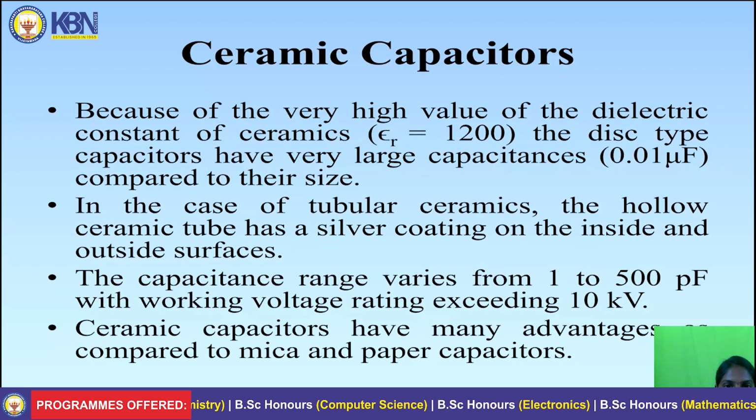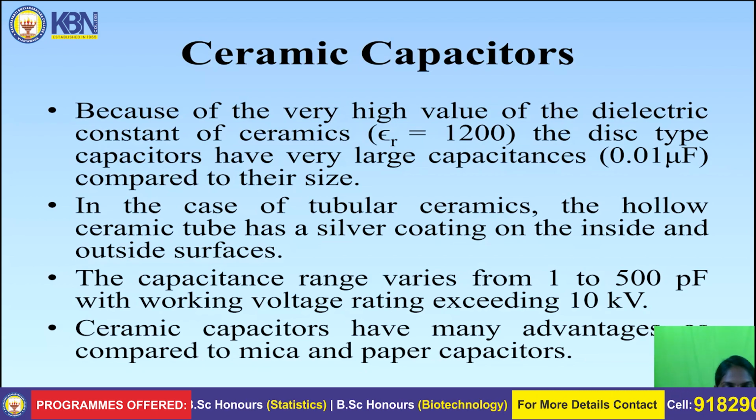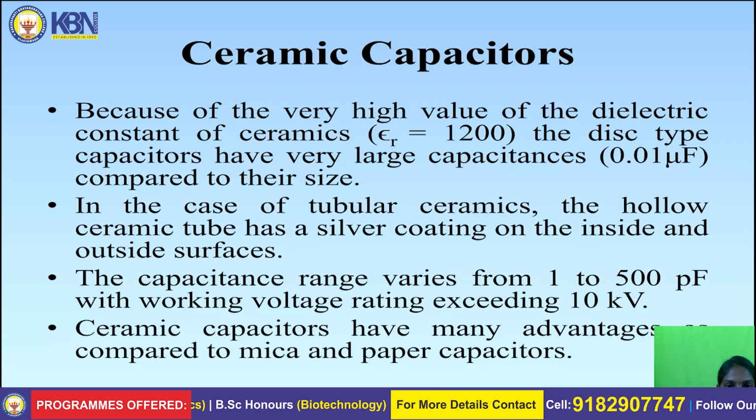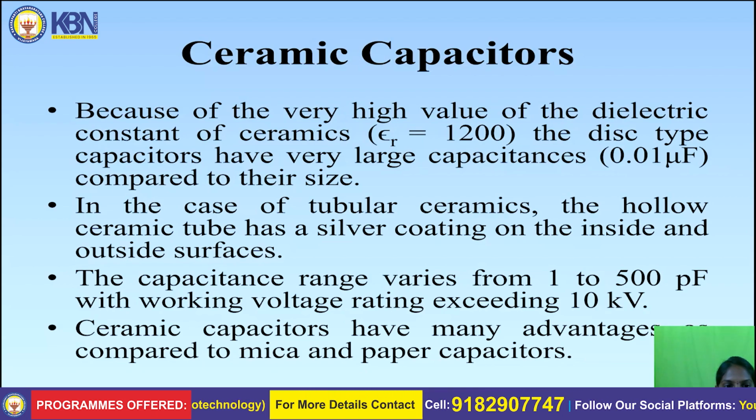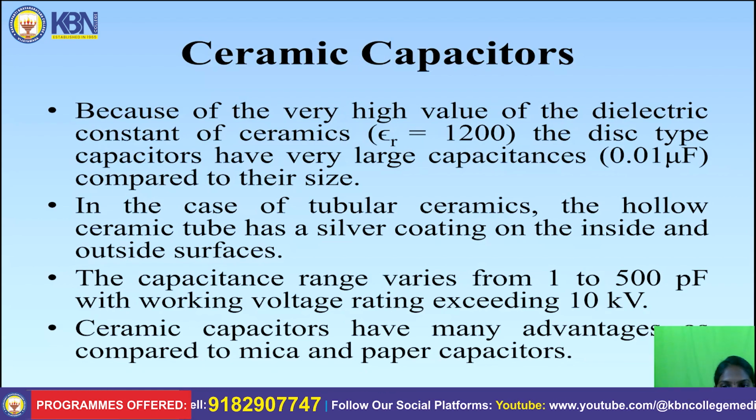Because of the very high value of the dielectric constant of ceramics, the disc-type capacitors have very large capacitance compared to their size. In the case of tubular ceramics, the hollow ceramic tube has silver coating on the inside and outside surfaces.